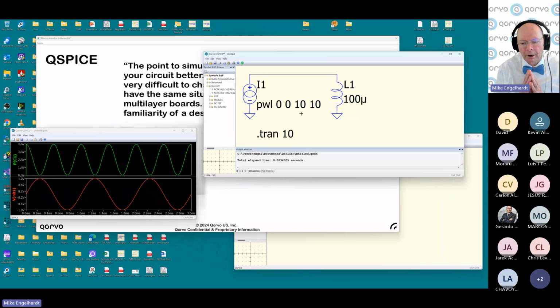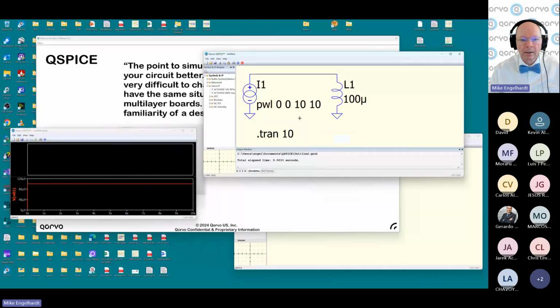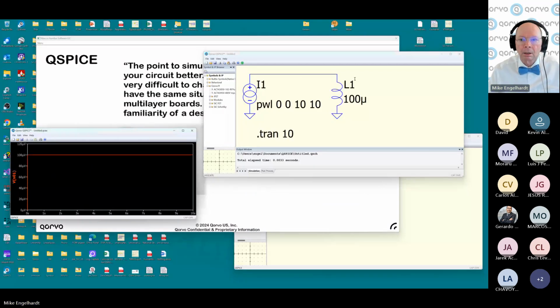Just like I can measure a resistance. If I put 1 amp through a resistor, I can read out the resistance as the voltage across the resistor. Well, in an inductor, if I put a unit dI/dt through an inductor, I read out the inductance as the voltage across the inductor. I'll demonstrate this here. I'll run this simulation, and we will plot. That's the output. See, it's 10 microvolts per 10 microhenry. So that's how I'm reading out the inductor.